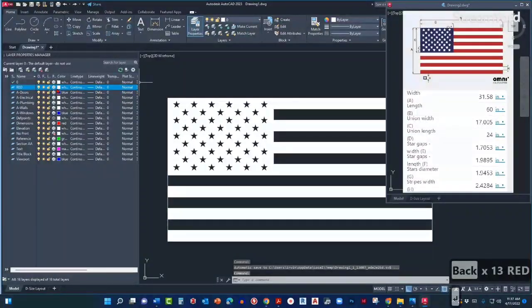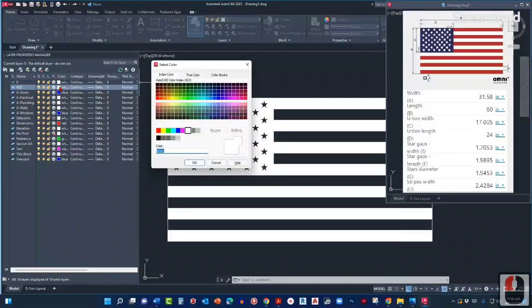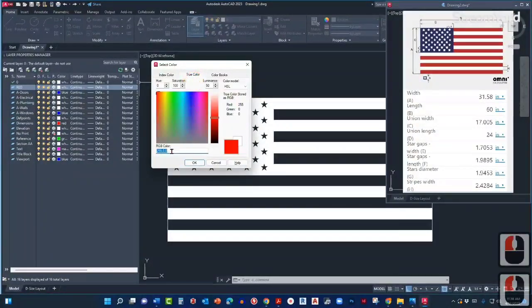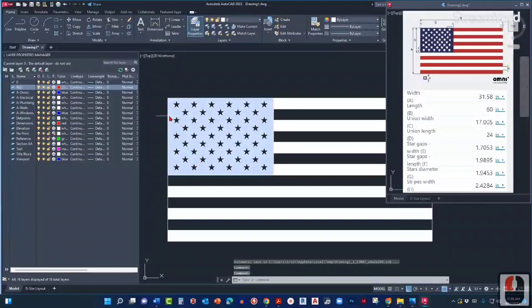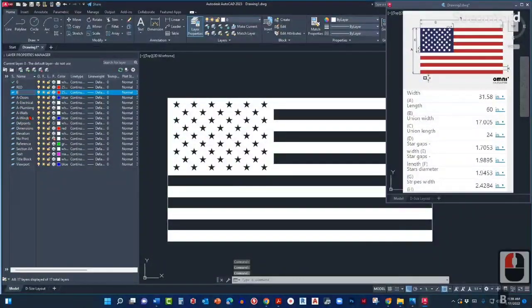So red. And then under the color option, I'm going to select this icon over here and click. So again, that's color, and go down and click. Let's change it to red, and let's go to true color. We're going to need this option in order to create our PDF with the true color red. So let's click OK, and then let's create 2 more layers using the same procedure.